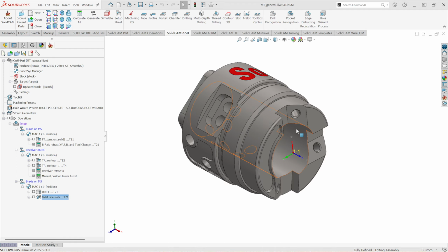In this video, we're going to continue programming our part features. In this case, I want to deal with these angled faces on the part itself. So we have to do a couple of different things. First things first, we don't have a coordinate system that's aligned to the angle of that face. So to initiate a toolpath, I'm going to go again into my profile operation from my 2D tab, Profile.